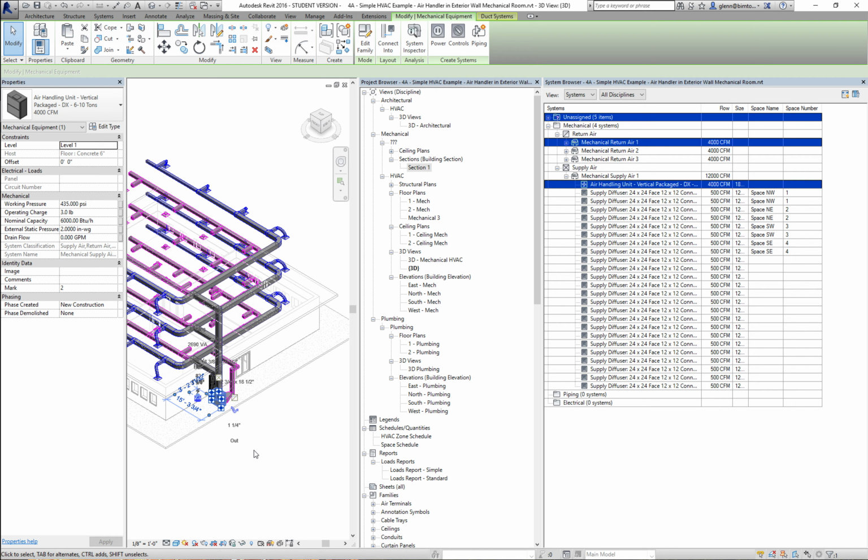Notice the air handler has not only a flow, but also some sort of capacity in terms of BTU per hour. That's going to get into the amount of heating and cooling, and whether this thing can actually take care of all the heating and cooling that's necessary. So it's a balance of figuring out the right size and how to make it all work together.